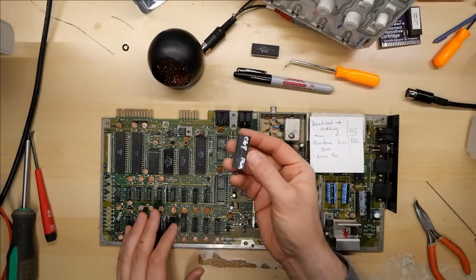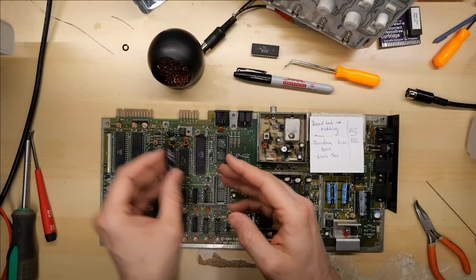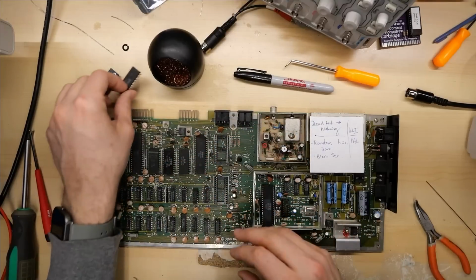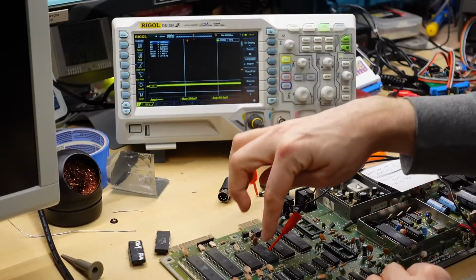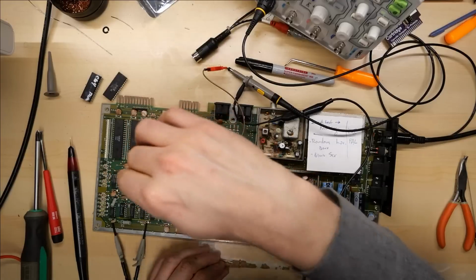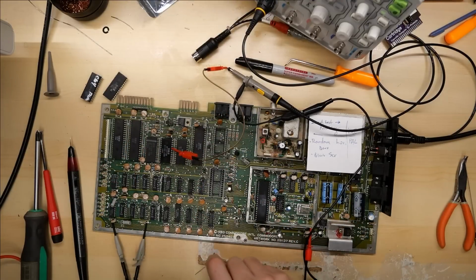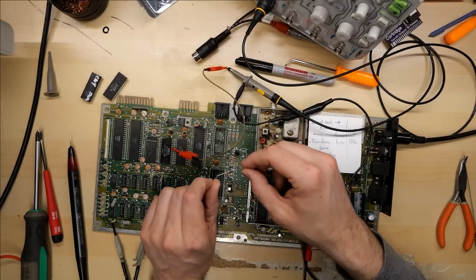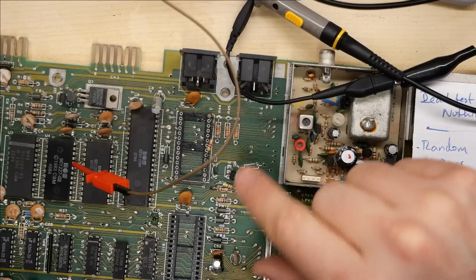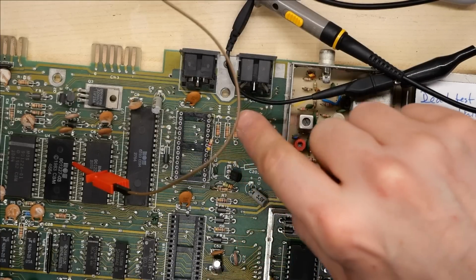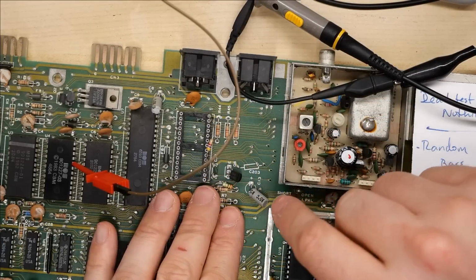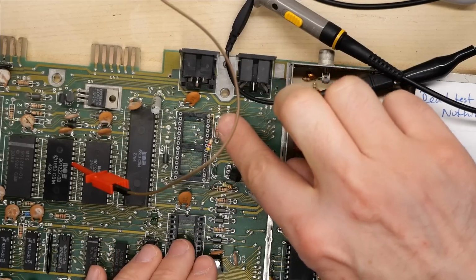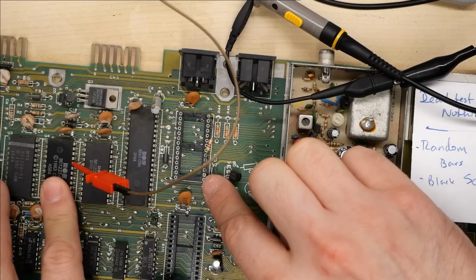So with the socket in there, I could just try this new PLA in there. But before I try that, I'm actually going to try a little experiment. The oscilloscope is connected to pin 20, which is the chip select line on the kernel ROM, the one I think might be problematic. The PLA is still out of the machine, and I have here a 4.7K resistor. I connected it between pin 28 and pin 16 on the PLA socket, which is 5 volts on pin 28 and the chip select line on the ROM here.